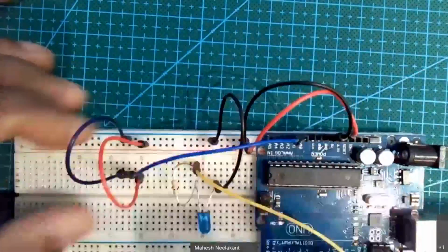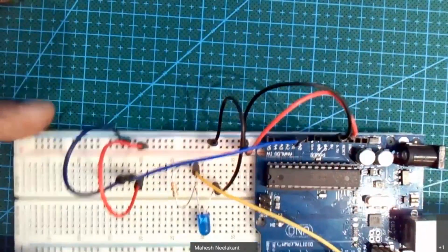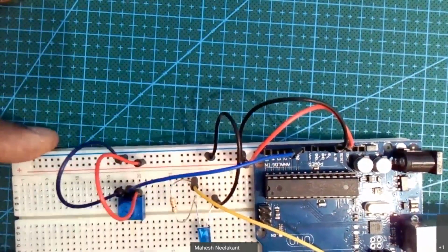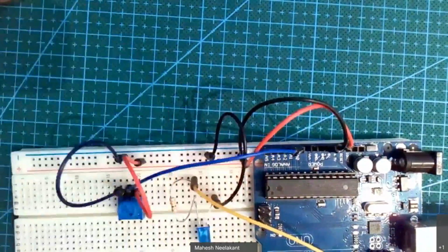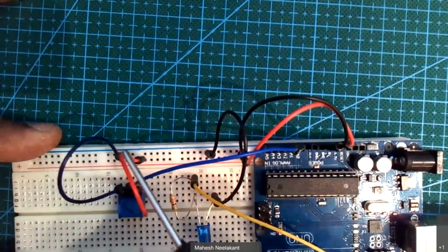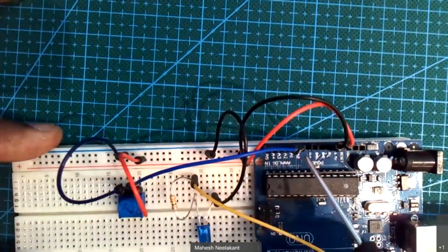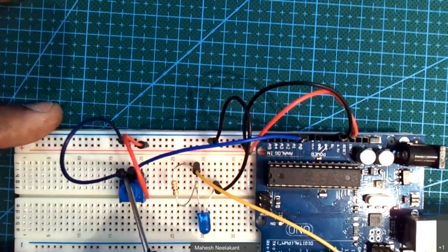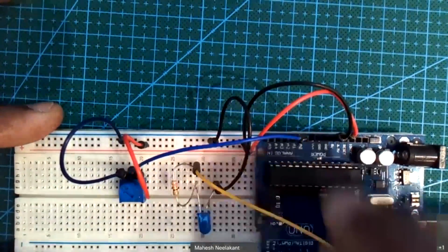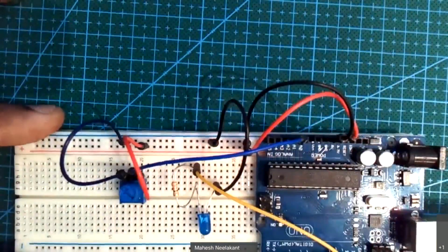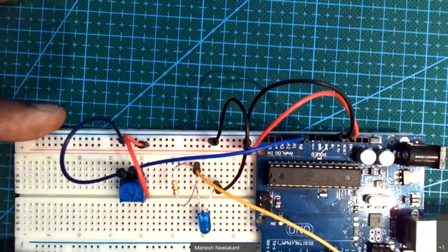A0. And we'll go over the wiring again, and then I'm going to connect up my potentiometer right there. So in this case, here's my current coming in. I'm closing the circuit, but the part that I want to read is the value of this resistor, and I'm actually doing that by connecting up the blue line up into a pin called A0. And we'll see why it's called A in just a minute, because it's an actual analog signal. We'll talk about analog signals in just a minute, but that's the wiring.